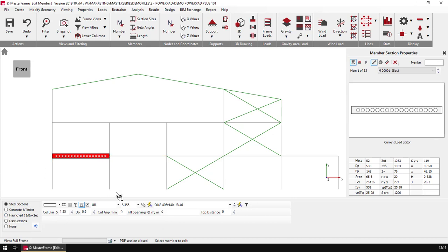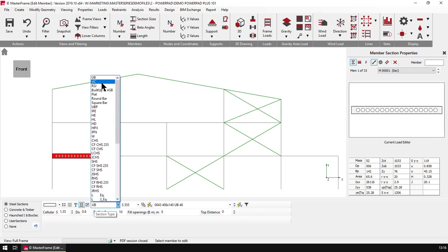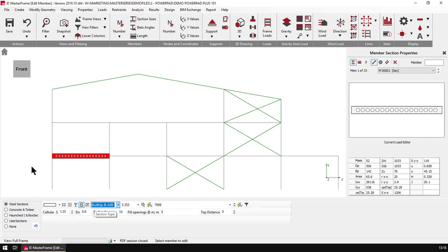We can also take another beam, and we could say, well, actually we don't want to use a beam, we want to use a built up section. So we're able to say that we actually want a section that is 500 exactly deep, with 200 flanges, 15 mil thick, and a 10 mil web, and that then is going to use that built up plate girder section.